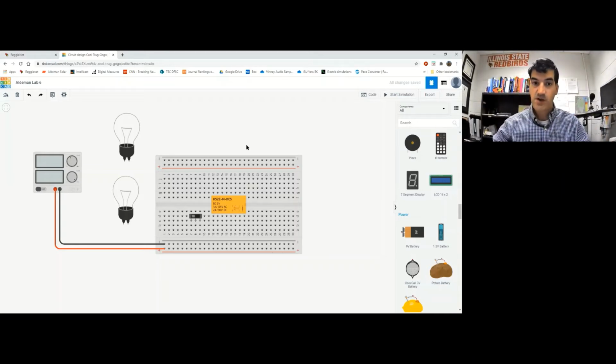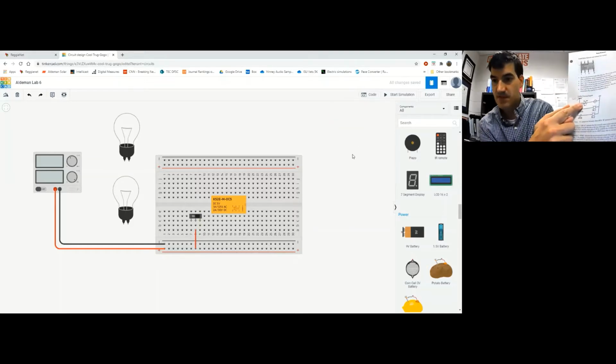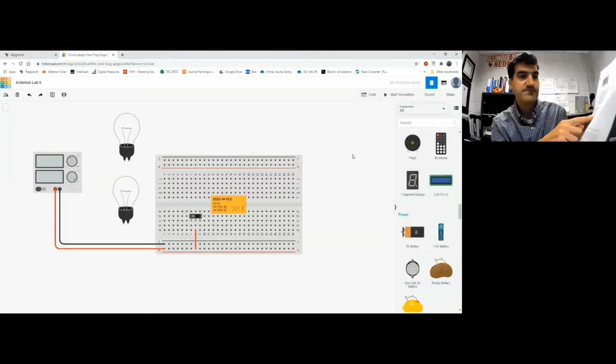All right, so go rung by rung in your ladder electrical diagram, and then within each rung, go left to right. That's the way to keep things organized. Otherwise, I just about guarantee you will mess something up. I would, for sure. All right, so I'm going to go from the positive side of my power rail to the common of my selector switch or my slide switch. And now I've got this wire taken care of.